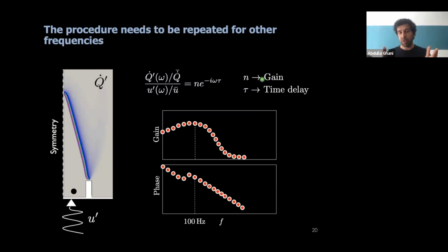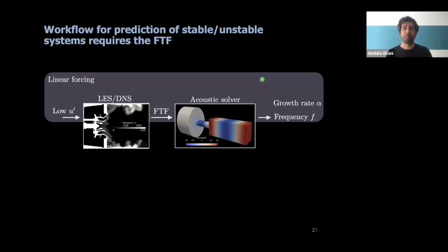So we have now this flame transfer function, and we see that computationally, this is expensive. For an experiment, doing a frequency loop to get this flame transfer function is not the most expensive part. I will explain this image in a minute. There is a work methodology based on these flame transfer functions, which are the key element that you need for thermoacoustic analysis to understand if your combustion system will be unstable or stable. So it's a prediction tool.